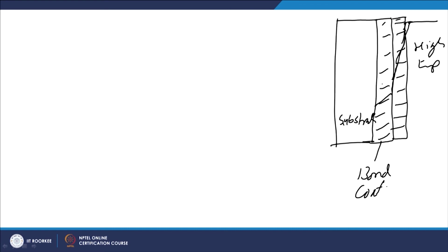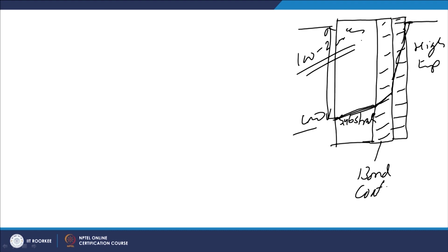Normally nickel based systems are used, which are of lower thermal conductivity, and then this is the low temperature side. So, this is the low temperature side, this is the substrate, a little bit of increase in temperature, then a further higher temperature in the bond coat, and so we can see that there is a clear gradient. This difference in temperature from one side of the substrate to the other side of the TBC material can be of the order of 100 to 200 degrees centigrade, depending upon the TBC material applied.